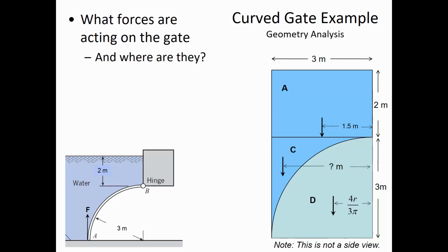Again, let me just go back to showing you what was B. B is all of the water that is beneath the hinge over to A and then 4 meters into the page. So there's this rectangle of water, B, and the reason why we calculate it is it's kind of an intermediate step. Once we know B and we've calculated D, then we can calculate the weight of the water by subtraction.